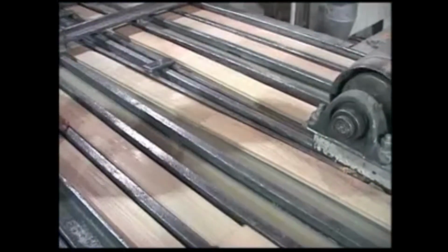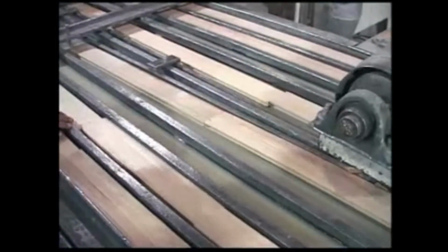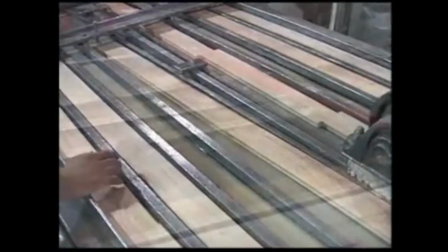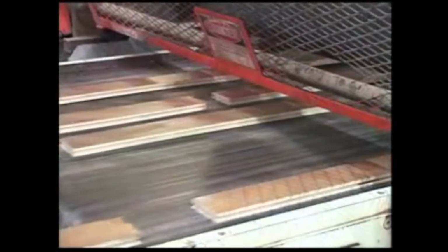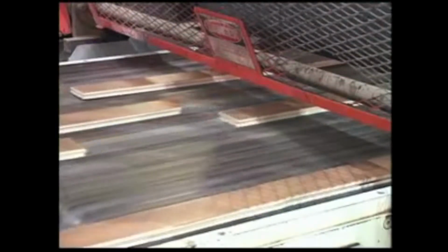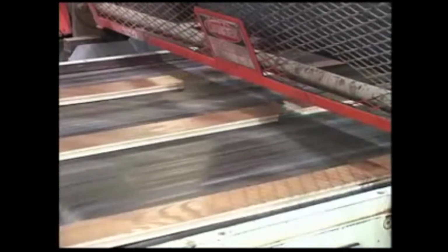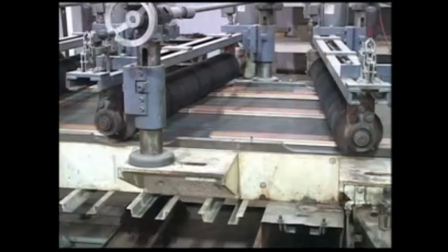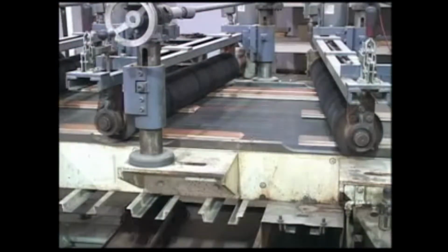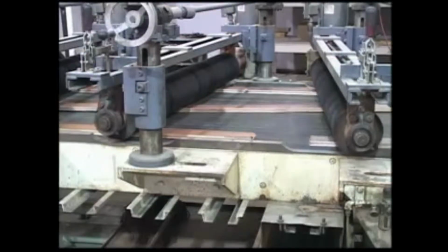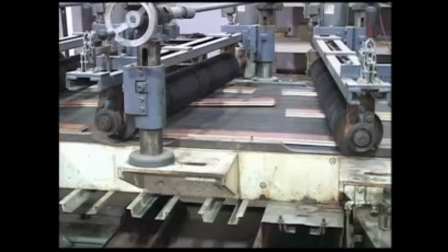The strips of wood are sanded one last time before a series of surface fillers, stains, and polyurethanes are applied, filling the open pores of the wood to create a smooth surface. Some of the thin polyurethane coats have aluminum oxide, increasing the durability and scratch resistance of the finish. Light sanding or brushing in between applications of the finish coats is common. This allows uniformity and consistency of coats, especially on boards with beveled edges.